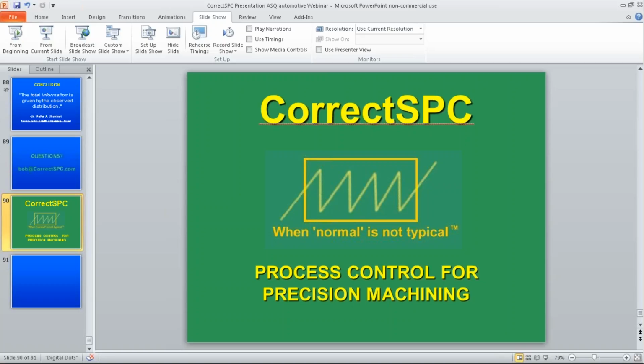But in general, I believe it's not a good thing because you're losing incredibly powerful information by having the machine do what you wouldn't want an operator to do, which is sit there and constantly adjust it. Remember, with this process, it only works if the operator only adjusts it when it hits a control limit and adjusts it to the other control limit. If they're constantly adjusting it, you can't use this approach, because now you probably will have random variation about the